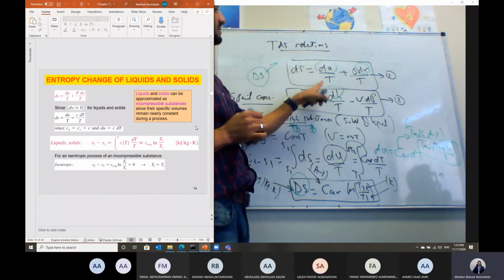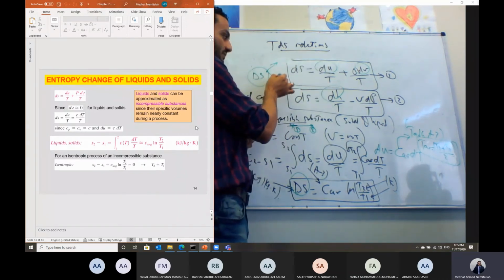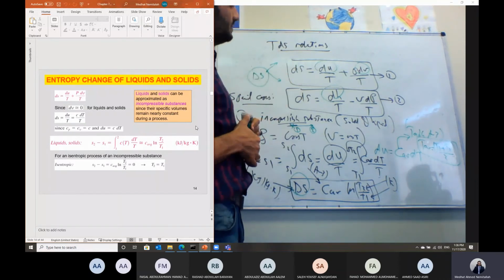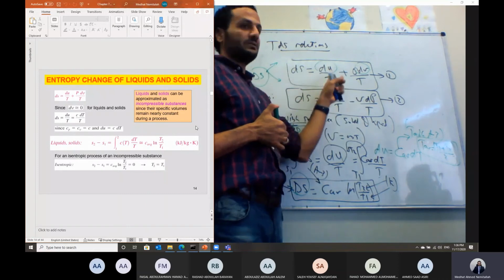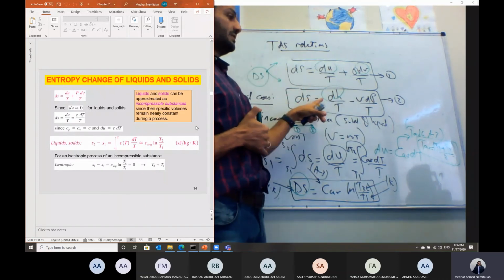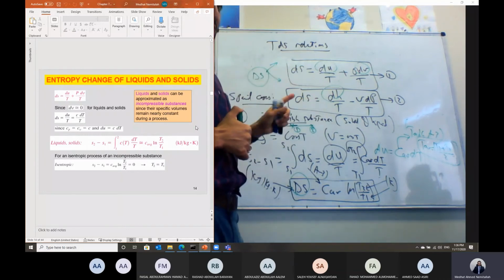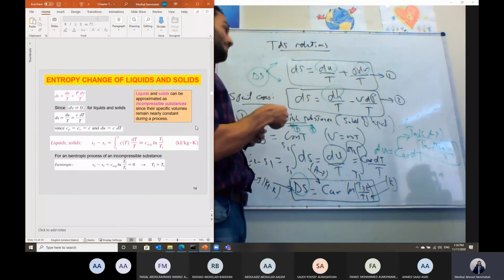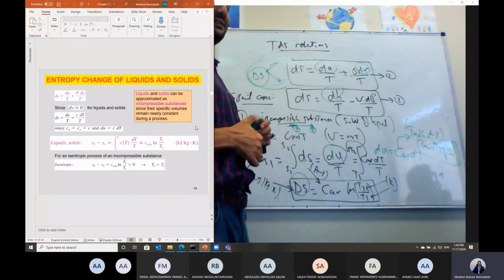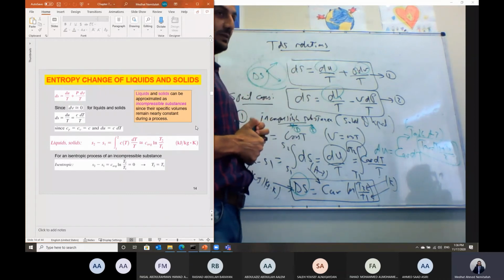Okay, we can consider Cv and Cp as constant, and then we can do the constant specific heat analysis. For the variable specific heat analysis, inshallah, we will reformulate this formula and come up with another formula to get it as a function of the entropy, and the entropy will be calculated from tables A17 to A25 again. So let's forget about this right now. In case of ideal gas, inshallah, next time we'll learn how to calculate delta S.